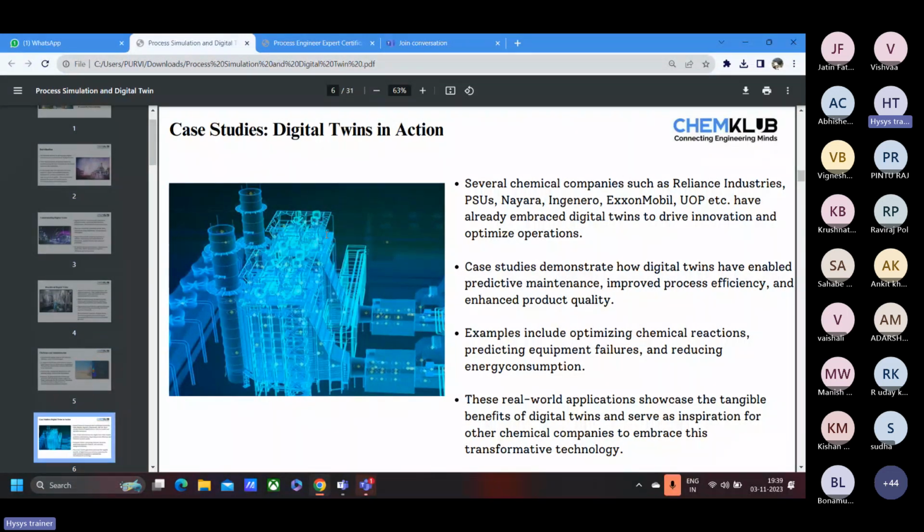Okay, so how they can achieve net carbon zero is by reducing the carbon dioxide emissions. And how they can do that is by reducing the energy consumption in their plants. And how you will know that this compressor can run on reduced energy, or if a certain compressor is running on HP steam of 200 ton, if you reduce, for example, to 180 ton, then also there is no issue with respect to compressor efficiency. So that 2 ton per hour multiplied by 24 multiplied by 365 days.